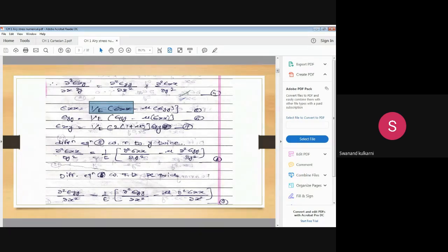that the forces are tensile in nature, and in both the x and y directions the forces are acting in tensile directions. That's why in the x direction this will be positive, but in the y direction this negative term will be present along the x-axis. So from that point of view, epsilon x, the strain along the x-axis, will be 1 upon E into bracket sigma x minus mu into sigma y. We consider this as equation number 5.